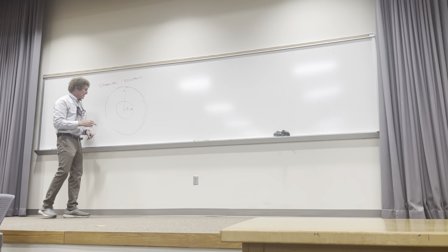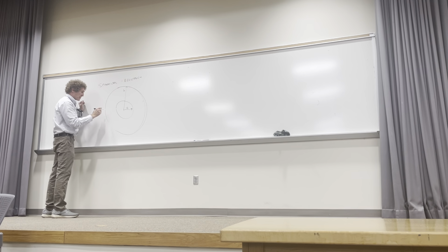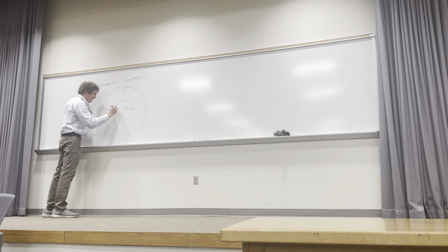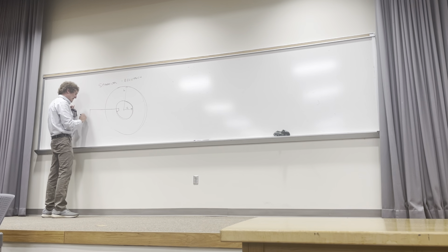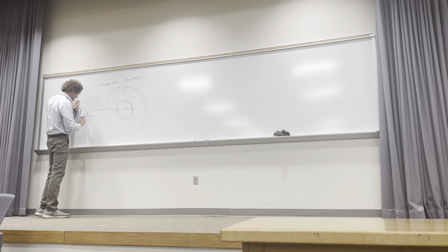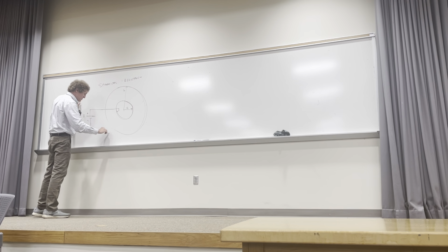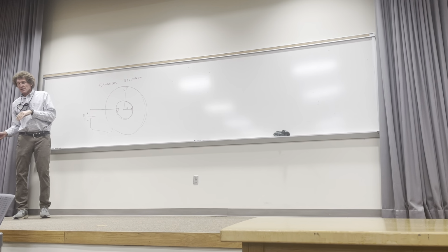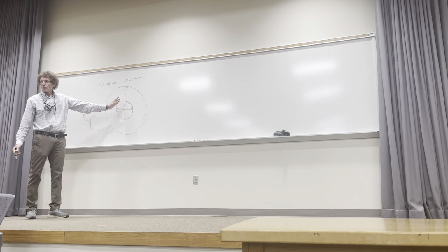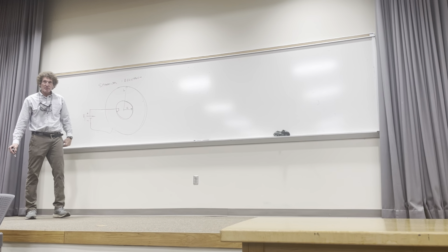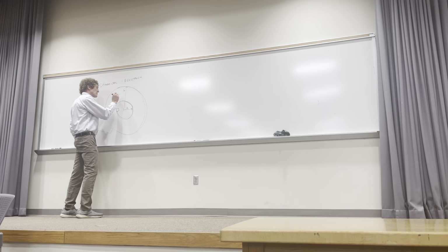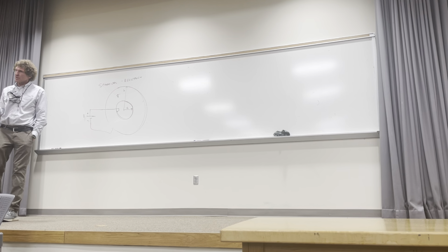And then bear with me. I'm going to dig a little tiny hole through there, and I'm going to take a wire and put it to this surface, and assume this inner surface is metallized. And then I'm going to put a battery here. I'll just call it V. And I'm going to assume the outer surface of that sphere is metallized. So think of a hollow sphere. It's got aluminum coating on the inside, and on the outside it's aluminum coated, but inside, between these halves, you have some material with a value sigma. So the current is flowing radially outward.